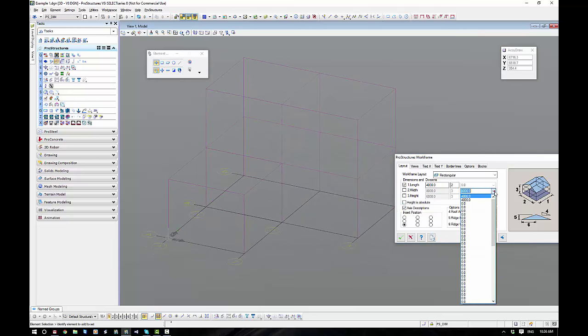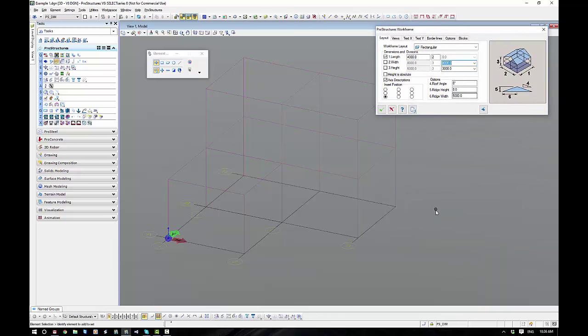Now, one of the things to watch out for is if we keep filling these out, but one of them is a very narrow one. I've got standard 4 meter grids, and one of these is short, like 2.5 meters. Just be careful, check your work. If I put one in at 2.5 meters as an example, check it's on the right end, that it's where you want it. You don't want to fill out 15 grids only to work out that you've put them in back to front. So just check your work as you go. Don't just assume it's right as you're typing centers in.